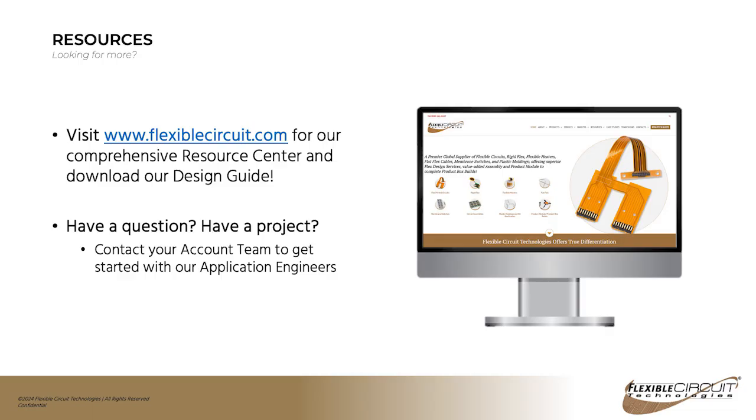Yes, you can. It's usually not silver chloride. It's usually silver epoxy. Silver chloride is typically used for membrane switches where you're putting it directly down onto a polyester substrate. If you're going to be going over polyimides or on copper, we typically use a silver epoxy, and that's something that's been done for many years. So it's a very standard process.